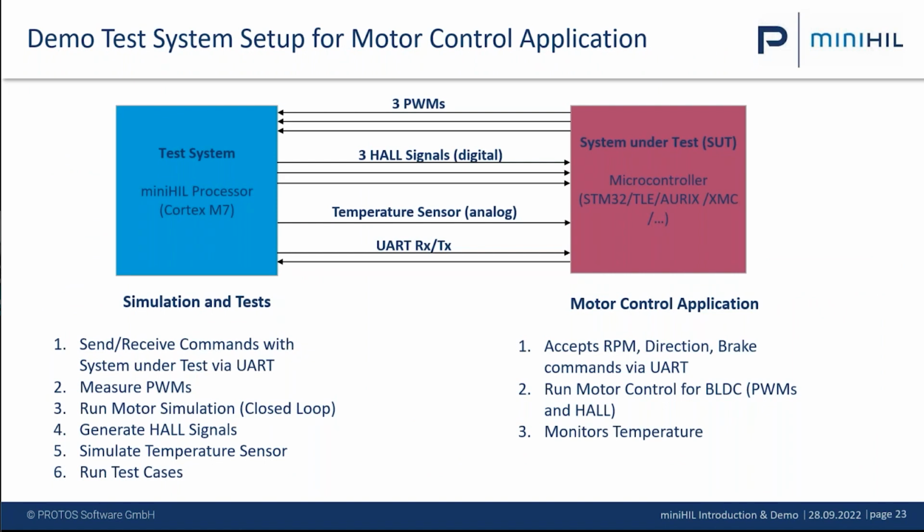Let's have a look at a demo I'm going to show you. That's a typical BLDC motor control, 3 PWM, 3 Hall signals. Here we run the environment simulation, so the motor plant simulation, and the simulation for the temperature sensor. And now we can do a lot of different things.